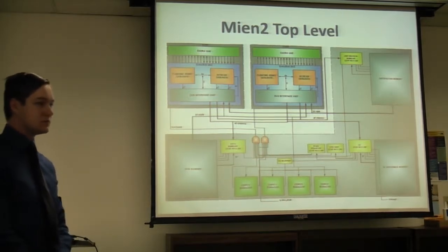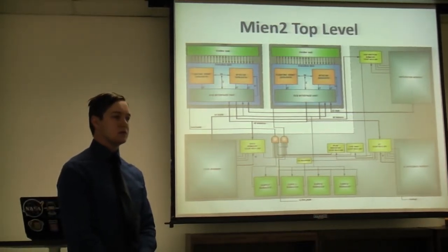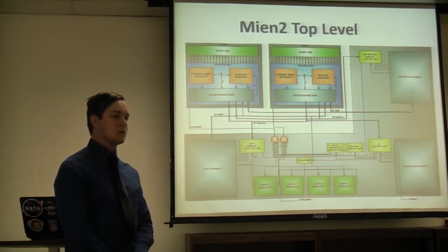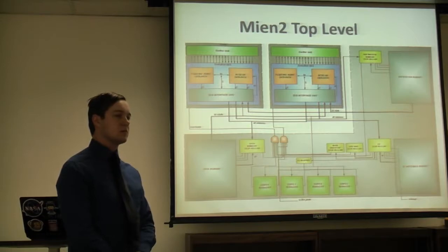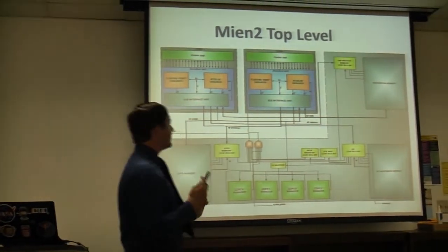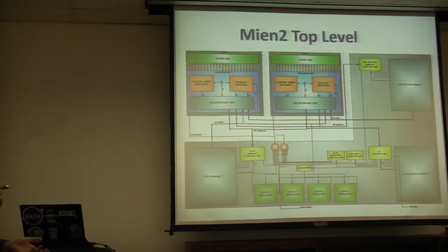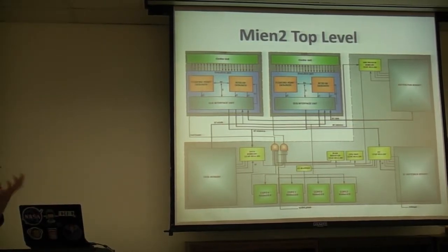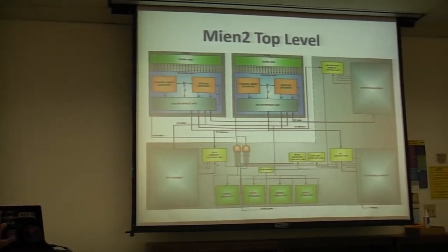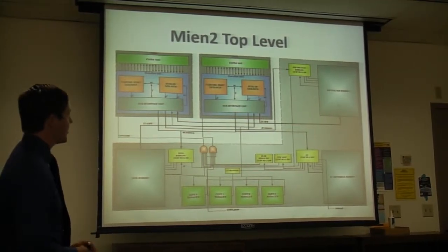Okay, so you talked about prioritizing the cores, running the instructions. Now, from what I gather, they don't just take turns running instructions, right? They don't switch off. There has to be some kind of algorithm that the compiler produces as to why one core is executing an instruction depending on what it is. Like, when does the other core start executing the next instruction, or is it something more complicated? No, it's a fairly simple approach. If both core 0 and core 1 are requesting, say, data memory, core 0 will get the data memory first. Core 1 will have to wait until core 0 has finished accessing data memory. That's the approach we took.